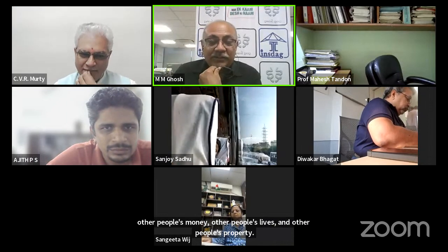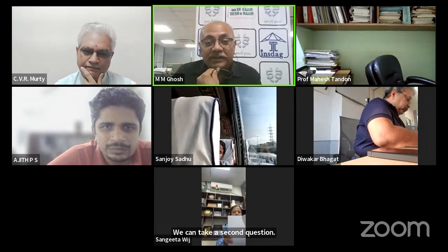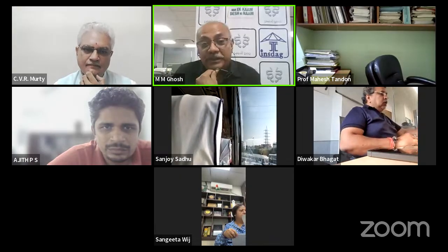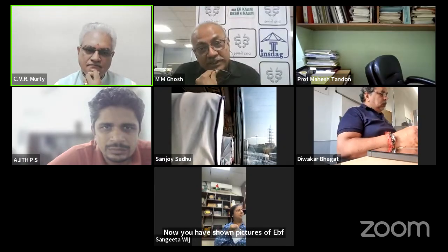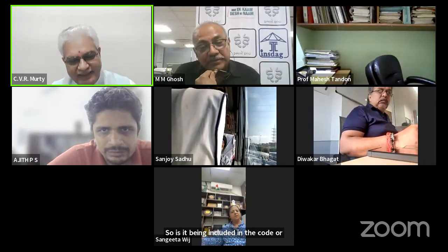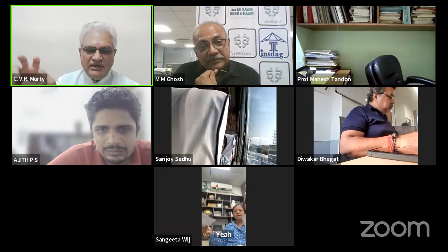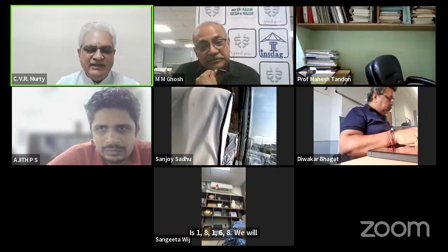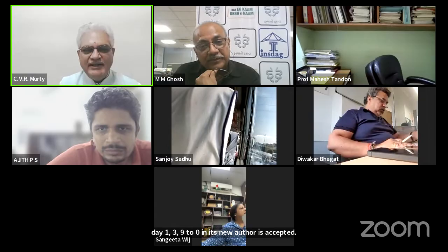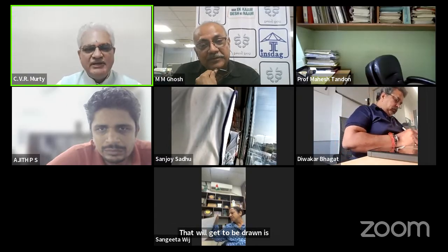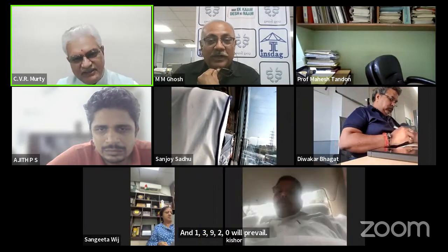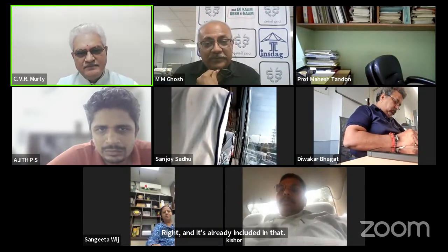So the second question is, we are comfortable with the CBF, the concentrically braced frame. Now you have shown pictures of EBF. Is it being included in the code, or is it included already in the new standard, which you have, IS 18168? We will drop IS 18168 the day 13920 in its new avatar is accepted. That will get withdrawn. IS 18168 will get withdrawn, and 13920 will prevail, right? And it's already included in that. Eccentric brace frames are already allowed.